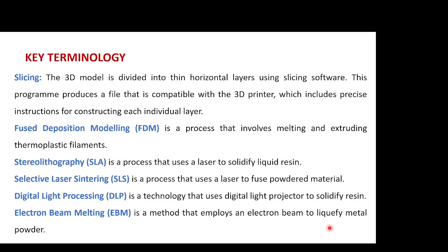Now, some key terminology that we often use in 3D printing is slicing. We've already seen what a slicer is. It's software which uses the digital model to create instructions for the 3D printer. Correspondingly, slicing, what is it? The 3D model is divided into thin horizontal layers using the slicing software. This program produces a file that is compatible with the 3D printer, which includes precise instructions for constructing each individual